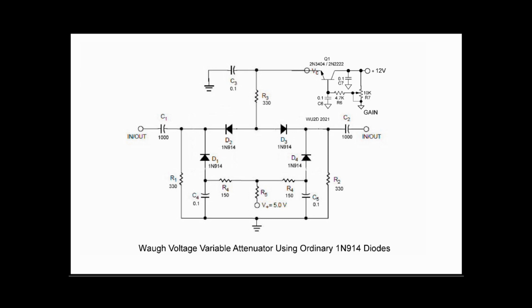Normally this would use pin diodes, which are more effective at microwave frequencies and allow more attenuation because of the way that they're built. The minimum isolation in the network is set by the capacitive reactance, the series reactance of the diodes. The use of 2 diodes in place of 1 increases the maximum attenuation and doubles the upper frequency limit for a given value of attenuation.